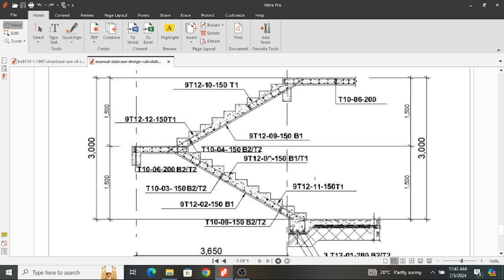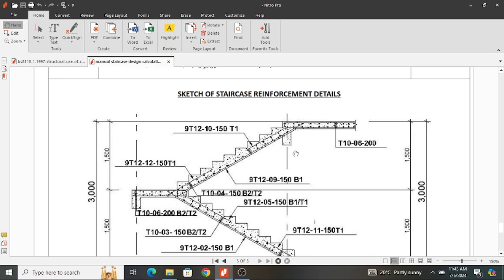And also remember, we introduced a beam in this section, so it's important you design this beam. Take the loading, distribute it to the beam, and also it is carrying the loading from the slab on the other side. So those two loadings will help you design that beam accordingly. That is where we have not provided reinforcement for this beam.